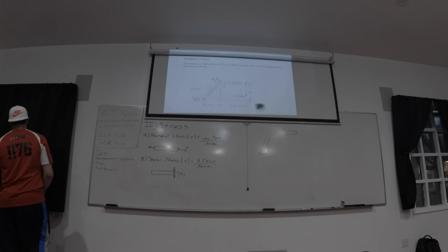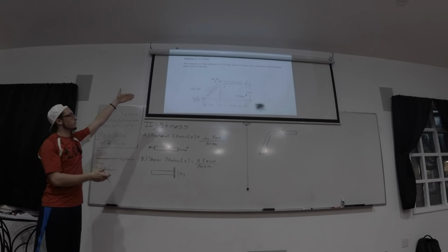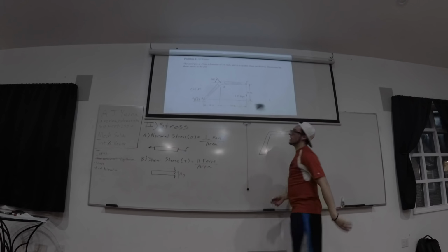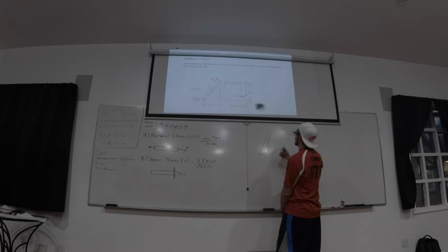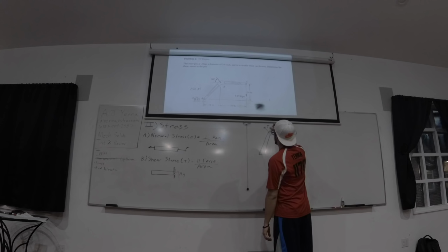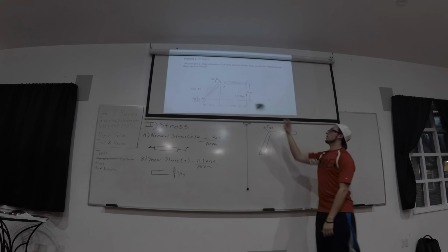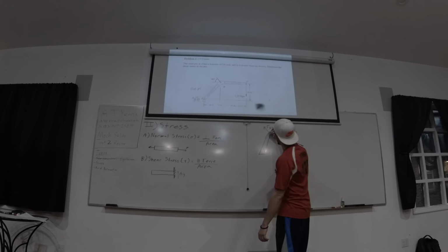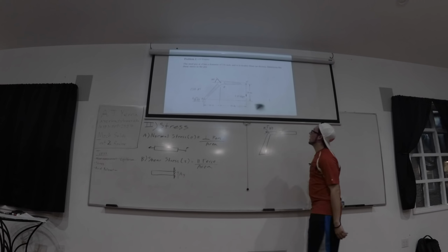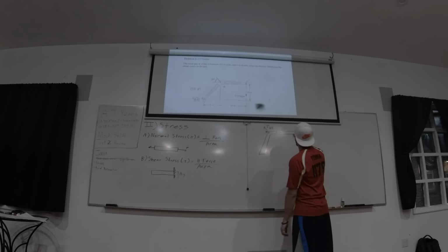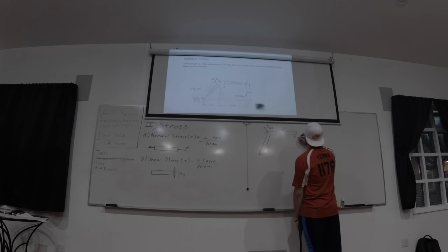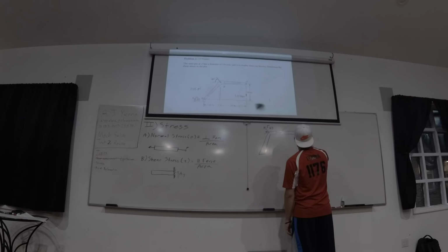Basically, it's a piece of string connected to the ceiling. So there's a tension at that point. The top up there was called point D before it got cut off. So I notated this guy, force in BD. That's essentially what it breaks down to. This guy is 50 degrees. It gives you the 3.25 kips. Just as a reminder, a kip is 1,000 pounds if it becomes relevant.